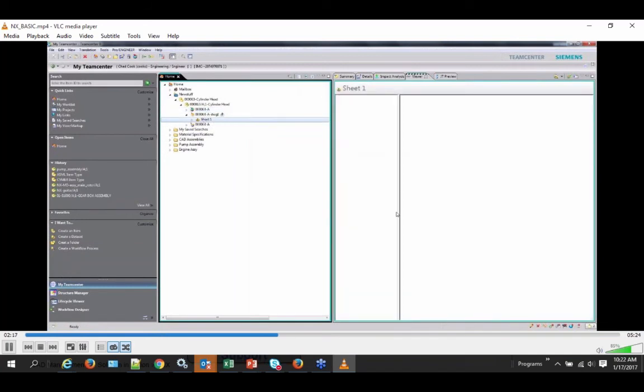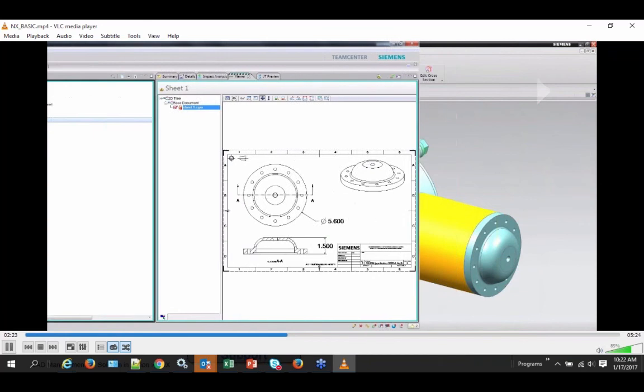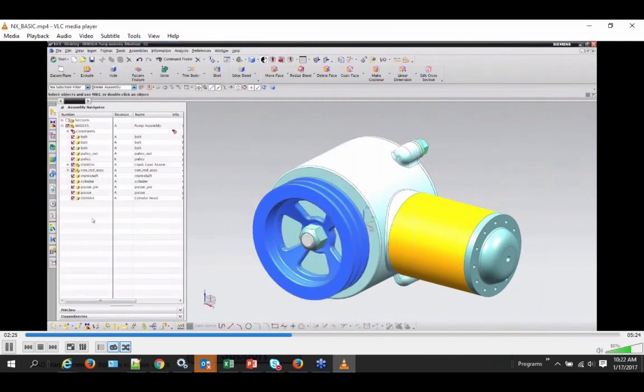Now it's not just the 3D CAD part file that got saved into Teamcenter. We also created a CGM of the drawing. And now again, people who don't have access to CAD can look at the drawing. Okay. So that was about creating a brand new part from scratch and saving back to Teamcenter directly from CAD, in this case NX. Now let's take a use case of searching for existing information and using that in the design.